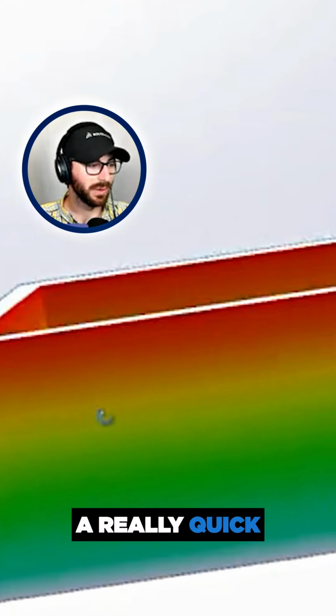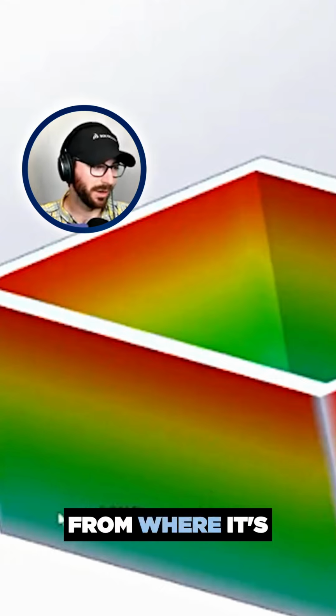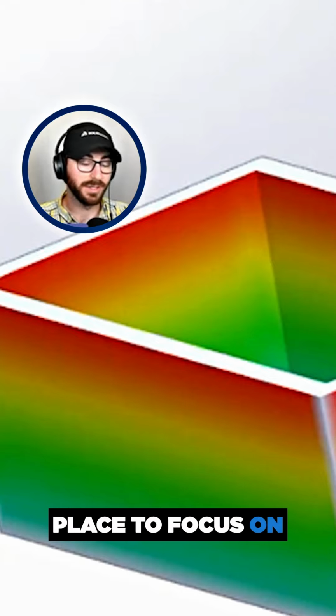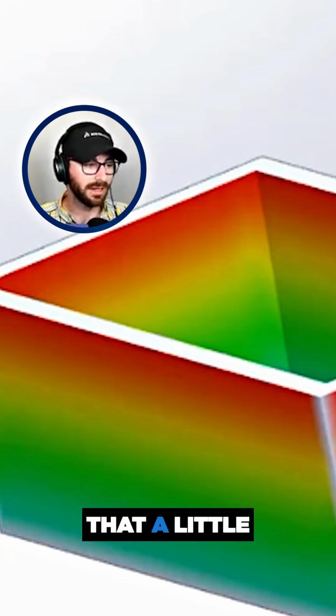So that gives you a really quick way to get an idea of, is this pretty gradual, or do you see a hard line here from where it's good to all of a sudden it's a dark red? And that's going to be a nice place to focus and make sure that you add some type of fillet or anything to make that a little bit more gradual.